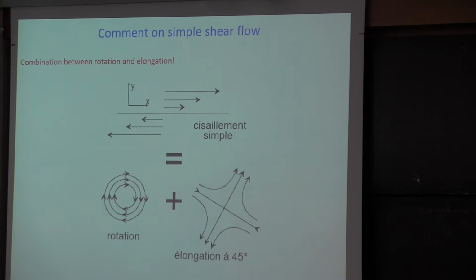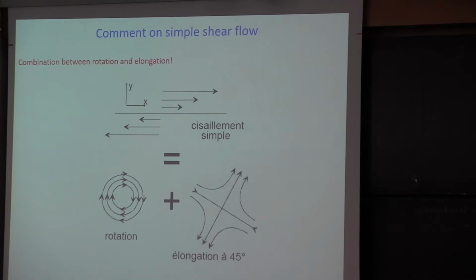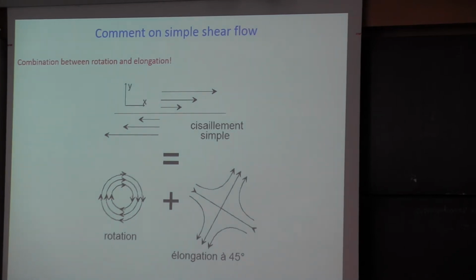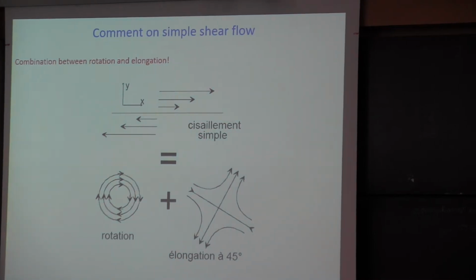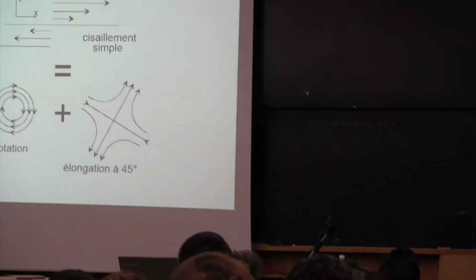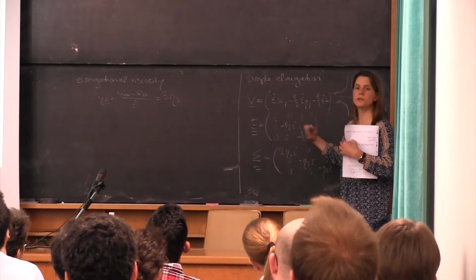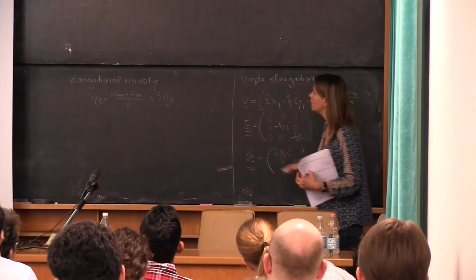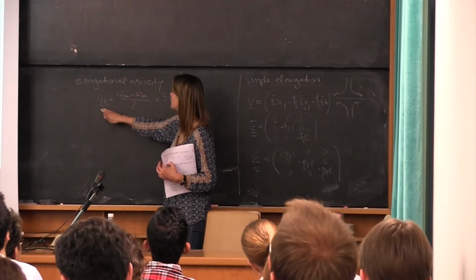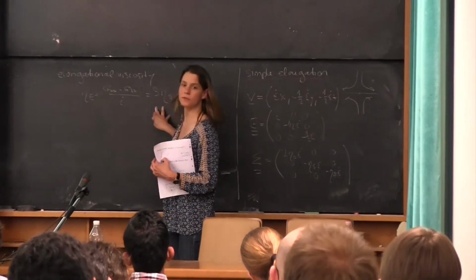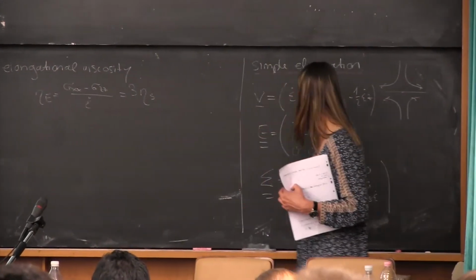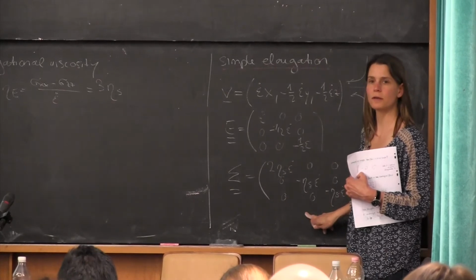Oh, yeah, okay. I agree. Actually, yeah, I think it should be like this. Yes, of course. Sorry. Yes, you're right. Absolutely right that here it's the same viscosity, because the link from E to sigma was just done using the constitutive equation. And it's only the definition of the extension viscosity which actually gives the 3 times eta s, which directly comes out of this if you write this correctly.